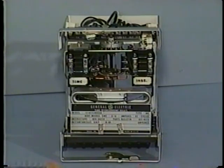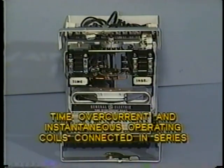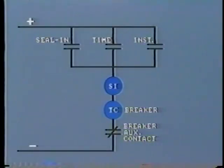Often the time-over-current relay includes an instantaneous element built into the same casing. As they must respond to the same CT secondary current, the operating coils are connected in series. The instantaneous relay tripping contacts are independent, wired in parallel with the time-over-current tripping contacts. Thus, in this typical trip circuit, either contact can complete the circuit and trip the breaker.